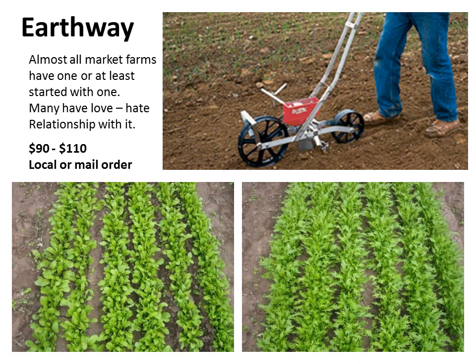Now on to seeders. Most market farms will start with a lightweight plate seeder like the Earthway seeder. Their main advantage over the older Planet Junior single row seeder is the weight of the unit. These work well when used alone or in multiple connected setups. Earthways work best with large, round seeds such as corn, beans, and peas. Smaller seeds tend to get stuck behind the seeder plates and are not as effective. There are some adjustments that can be made for smaller seeds, but most growers have a love-hate relationship with them.